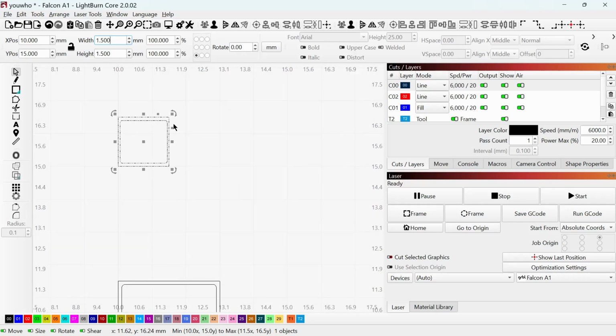Now I need to break up the group, so I ungroup it. Select the middle one again, and just to sort out the middle grout there, I've got to come up to this width here, and rather than 1.4, I'm going to put in 1.25 just to make the mortar the correct way. Now you see that moved in here, no, it isn't correct. Made a little mistake there, folks. So we Control Z that. Up here, I'm going to change the orientation to the centre this time. So I change it to 1.25. That is the correct size for the mortar.